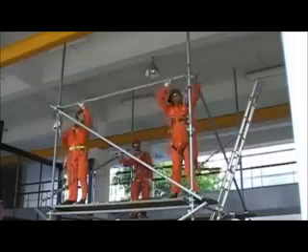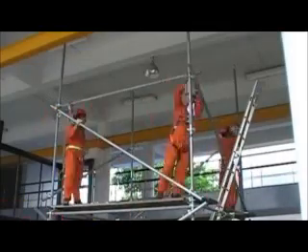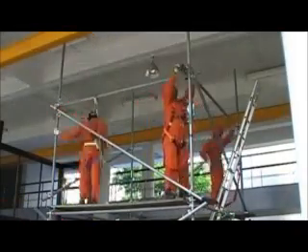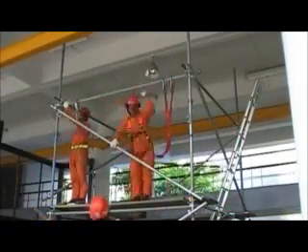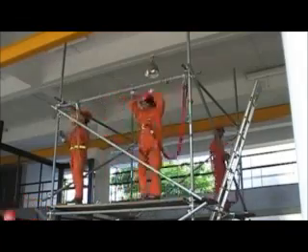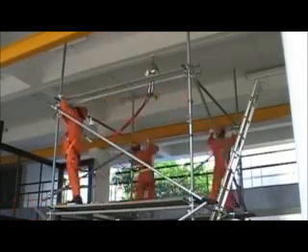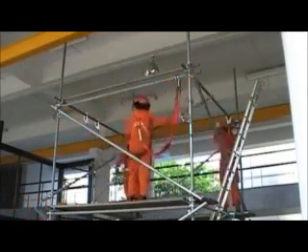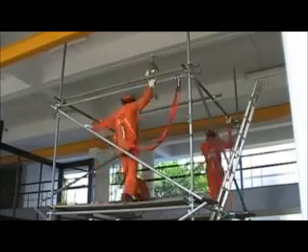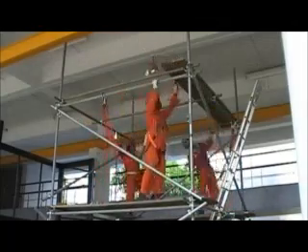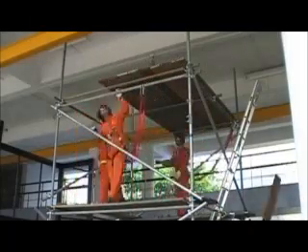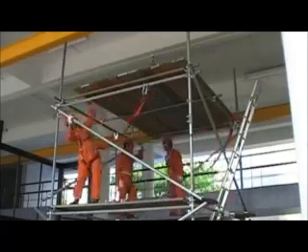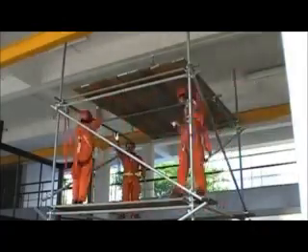Planks or jalis are to be used for making the platform. Number of platforms generally for light duty is 3, medium duty 2 and heavy duty 1. Gap between two planks should not cross 1 inch and they are to be properly locked and clamped. Width of each plank can be 10 inch and thickness 2 inch. Overhanging allowed for plank is 150 to 300 mm and minimum width of a platform is 900 mm.